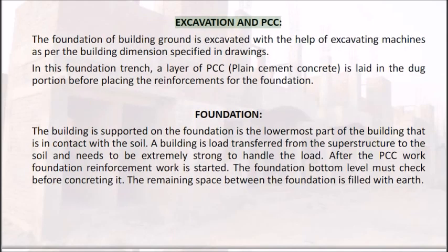Excavation and PCC. The foundation of building ground is excavated with the help of excavating machines as per the building dimensions specified in drawings. In this foundation trench, a layer of PCC, plain cement concrete, is laid in the dug portion before placing the reinforcements for the foundation.